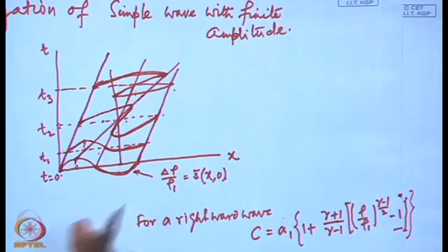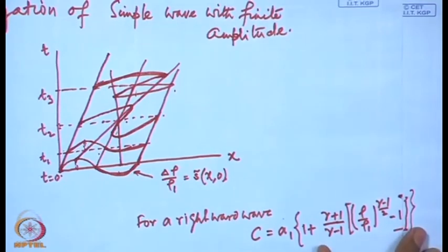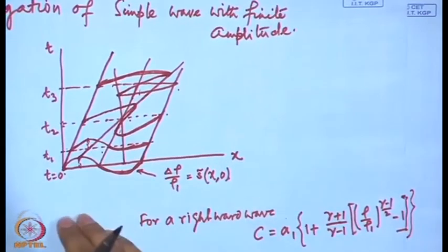Looking at this case, however, we see that the expansion wave always remains isentropic, and as it propagates it flattens, and the gradients are continuously decreasing. It never achieves any stationary condition, and the isentropic relations always hold over the expansion part, and since no stationary condition is achieved, there are no expansion shocks in reality.